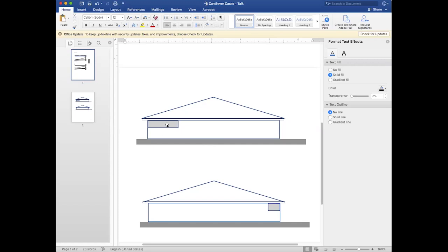So what I was tasked to do was to essentially support this corner of this hip roof all in a cantilever portion. And we were using sawn lumber at the time. So what could we use? Above this window, I think you can see my mouse, the cursor. Above there, we're going to have a beam that cantilevered and supported the corner of the hip roof.